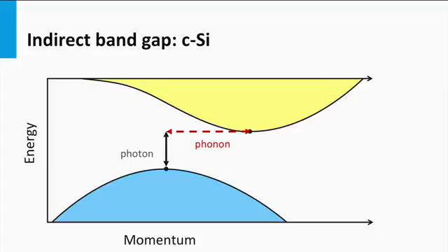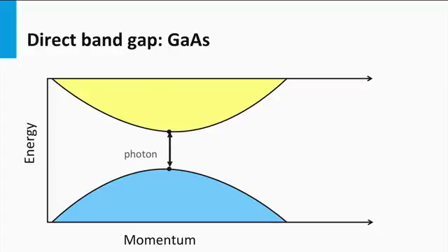Crystalline silicon is an indirect bandgap material. If we ignore Shockley-Read-Hall recombination by defects, the radiative recombination in an indirect bandgap material like crystalline silicon is inefficient and recombination will be dominated by the Auger mechanism. For a direct bandgap material such as gallium arsenide, under moderate illumination conditions, radiative recombination will be the dominant loss mechanism of charge carriers. For very high illumination conditions, Auger recombination starts to play a role as well.